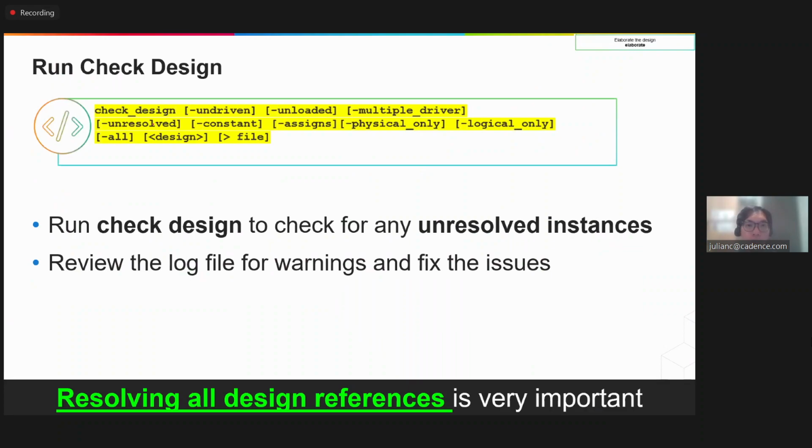Okay, so now you've already read the RTL and elaborated it. The tool, Genus, now understands your RTL very well and links everything together, and then there's a top design now, and there are also sub designs. So one thing before you proceed, please run a check design. We have a command called check design. This check design is very important. Basically, it does what the command says.